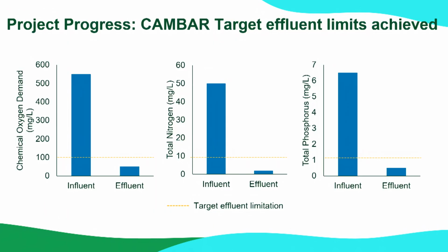So Kevin mentioned also that our next steps are going to be to focus on recycling wastewater and reusing it. And for reuse, there are certain regulations and target limitations for treated wastewater that we need to meet. So there needs to be a certain concentration of carbon, nitrogen, and phosphorus in the water that's treated, only after which it can be reused. And in the last 3 to 6 months, we've been seeing that compared to the influent wastewater, which is the wastewater we synthetically prepare in lab, our effluent or treated wastewater is consistently below the target limitation. So we're exceeding our performance metrics.